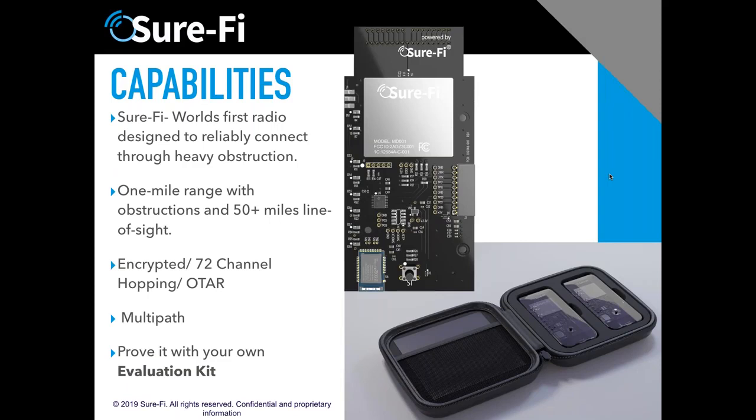For a door, we were just talking about it, yes, you can pull power from anywhere in the building, but with this new power box that we have, you can tie into the required exit signs or an always-on light in the hall and connect into that. It has its own backup battery, and this power box will allow you to use power right there. It has all the 12 volt DC out that you need to power everything.